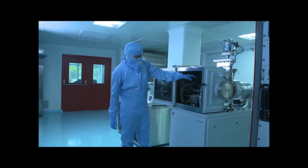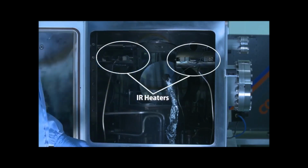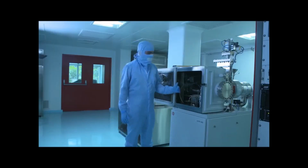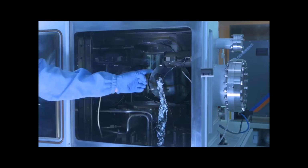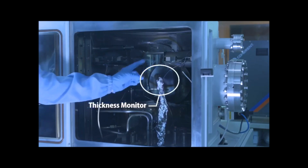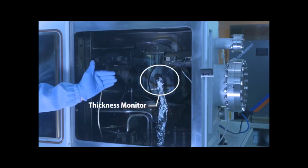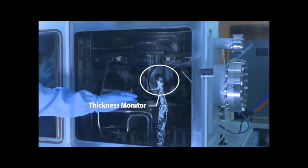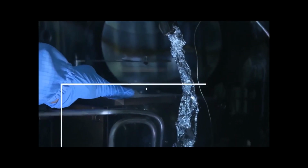Next part is the infrared heater, and this heater can be used to heat the chamber temperature up to 300 degrees Celsius, and sometimes it is required to get a very uniform thin film. Next part is the thickness monitor. In this thickness monitor, we have a quartz crystal monitor, and this QCM gives the amount of material deposited over the QCM. The lowermost part of this chamber is the heart of the system.